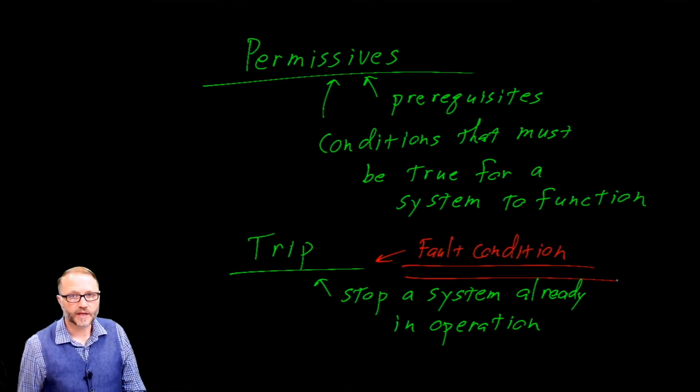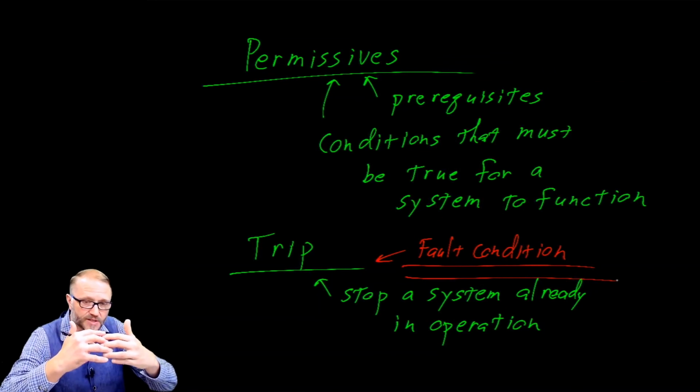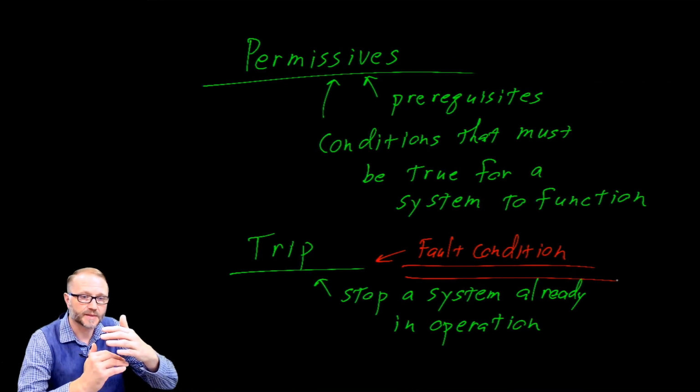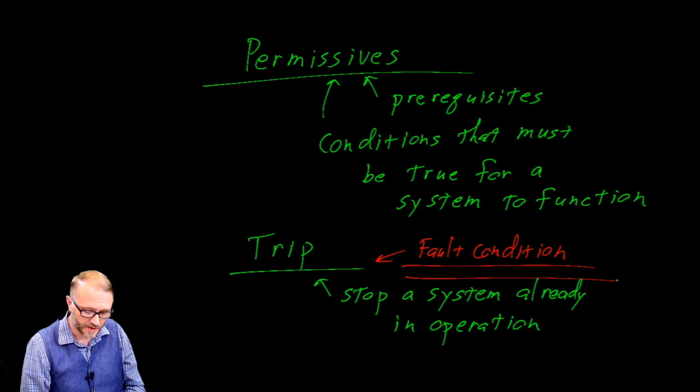By the way, we have to be careful when we talk about fault conditions. It's one thing to say, well, if the machine is malfunctioning, you mash the emergency stop button, the machine comes to a complete stop and life is good. But not all processes are so simple. As an example, you could consider a machine that's lifting a weight, and you can imagine a situation where somebody is underneath that weight. And if you were to hit an emergency stop, the weight might actually fall, causing additional injuries to that particular person. So a fault condition is very specific to the machinery on which we're talking about.